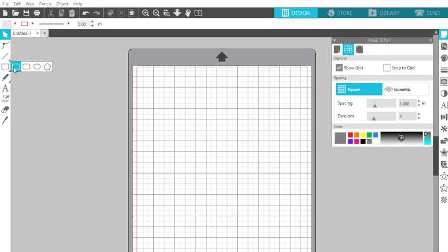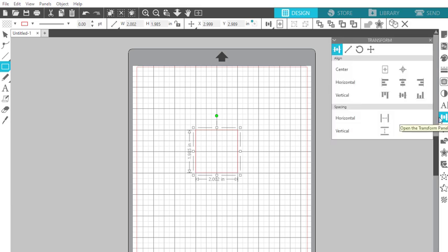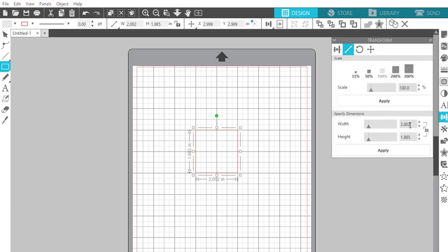We're going to select the Draw Rectangle tool and sweep out the base of the box. And in this case, we're going to approximate a 2-inch box, but we can go into Scale, and the Scale tool will allow us to say that we want it to be exactly 2 inches on a side. If we wanted, we could use metric and specify millimeters instead of inches. So now we have a box that is 2 inches on a side.